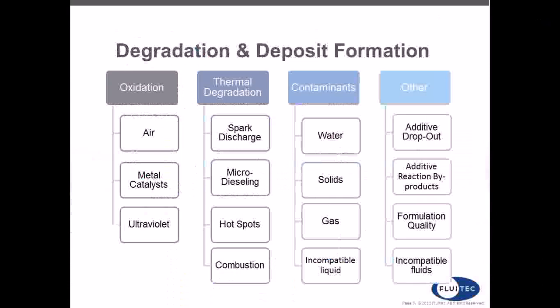In fact, we've seen some new oils that have failed once they've been put in use because they were stored outside in poly totes for too long. So it's just a form of degradation to be aware of. Thermal degradation is an event that happens much more rapidly than oxidation. Although it's similar and highly temperature influenced, thermal degradation typically requires temperatures in excess of 300 degrees C to really cause a thermal degradation reaction.